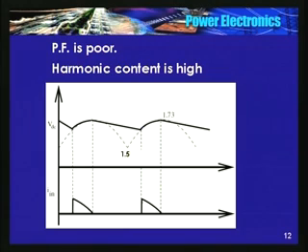See here, this dotted waveform is the uncontrolled rectification, a three-phase fully bridged uncontrolled rectification, each of 60-degree duration. Okay, the peak is 1.73 per unit. I have taken the peak of the phase voltage as 1. So we have drawn this waveform with peak 1.73 and minimum 1.5.